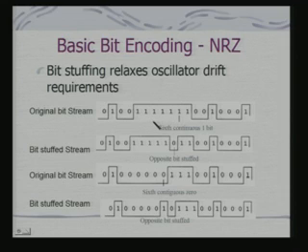So, how to minimize this problem of clock drift? What it uses is a bit stuffed stream. What it does is, it uses a convention, and at regular intervals it puts in an opposite bit, which is stuffed in between.